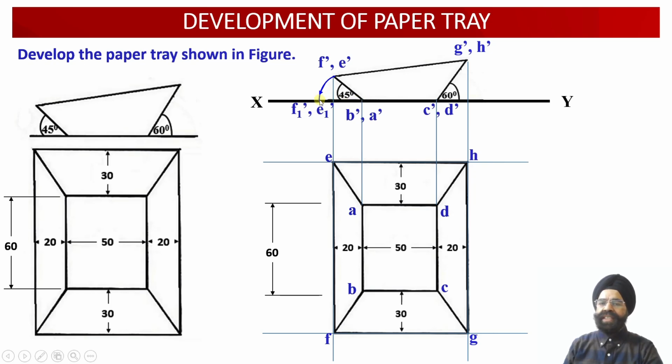Now since the apparent lengths in the new orientation, that is A dash E1 dash and B dash F1 dash, happen to be parallel to the horizontal plane, the projections of these 2 points E1 dash and F1 dash into the top view projections over here are going to provide us with the true length of the edges AE1 and BF1 over here.